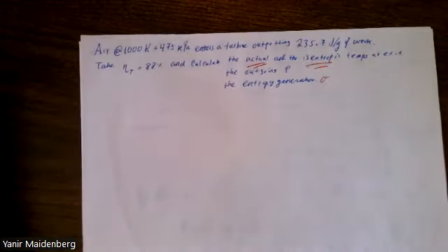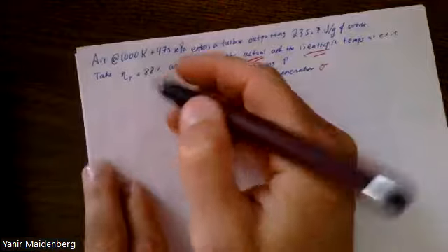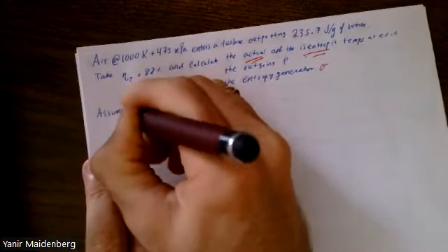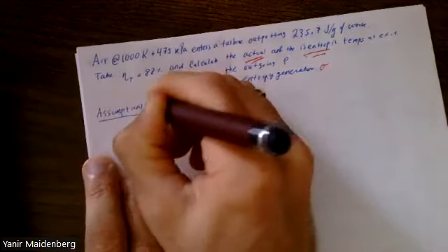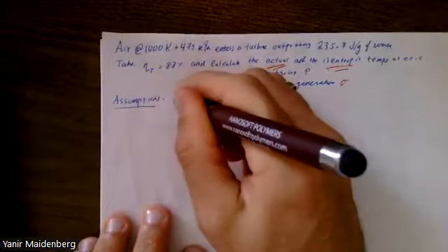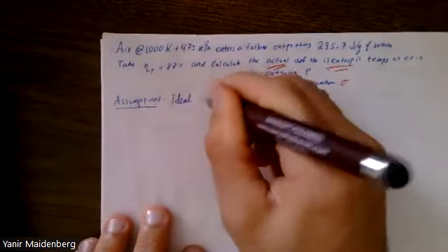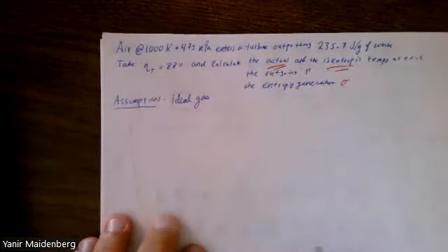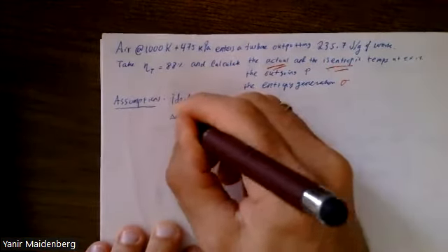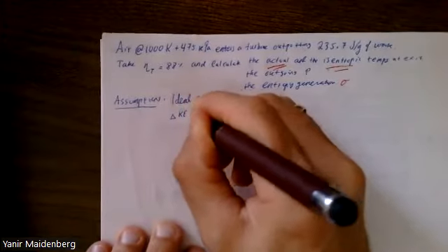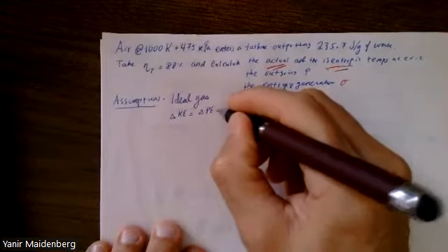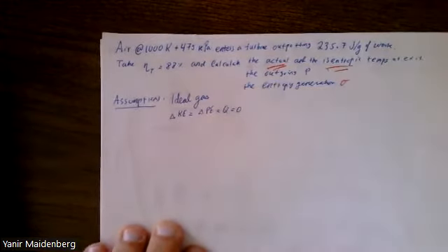Okay, so before we do anything, let's make assumptions. Whenever you have a gas that's not tabulated, it's a really, really good bet to assume it's ideal. So assume this thing is an ideal gas, which pretty much it is. You're also going to assume that since we're not really discussing much kinetic energy, there's going to be no kinetic energy, no potential energy, and this thing is also adiabatic.